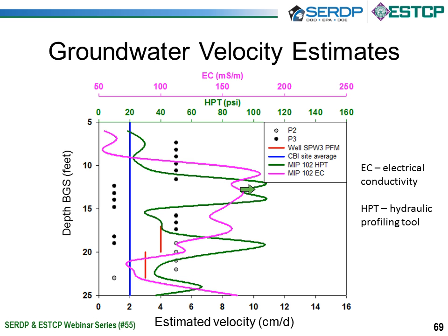And the high pressure corresponds to a low conductivity zone, and at each peak, we measured our lowest velocity. So almost a direct correlation with the high pressures and low velocities, which gave us a lot of confidence that the velocities that we're looking at are at least reasonable, given that they bracket all the other measurements of velocity and also correspond quite well to the hydraulic profiling tool.